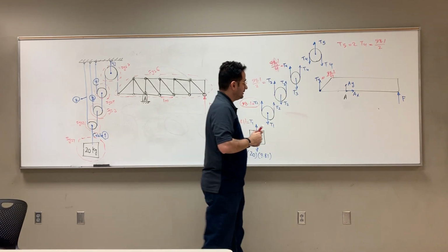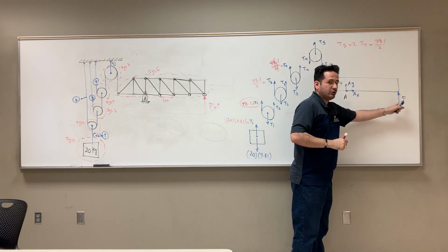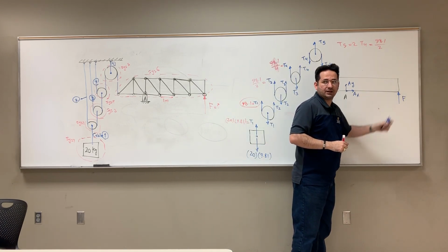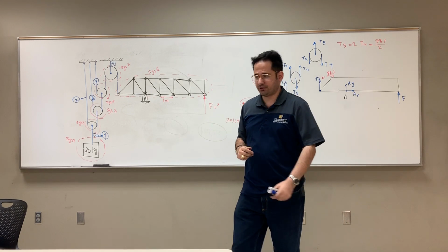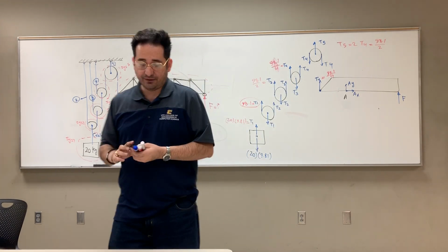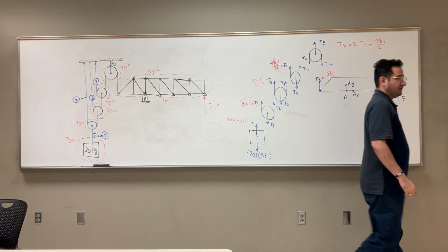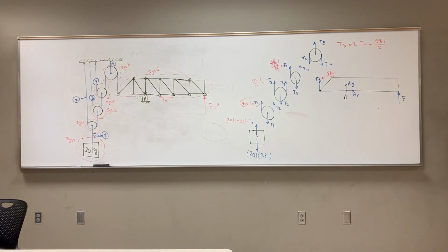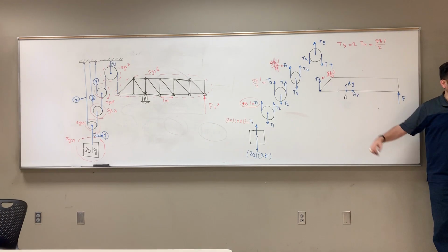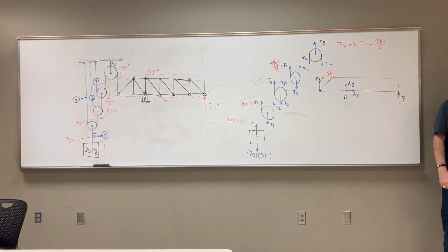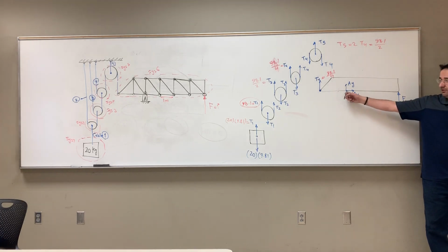Now, if I want to find F, let's say the question was to find the value of force such that it keeps the system in equilibrium, then what should I do? Do I bother to find AX, AY? No. I just write the moment around A to get rid of these.